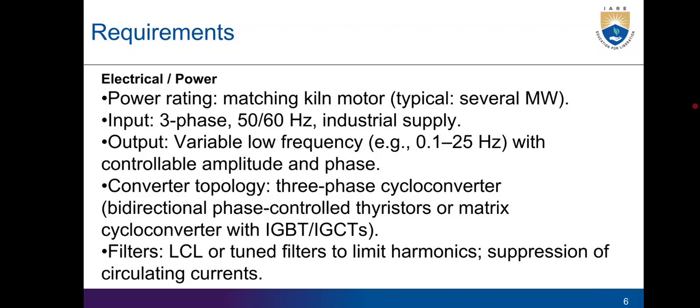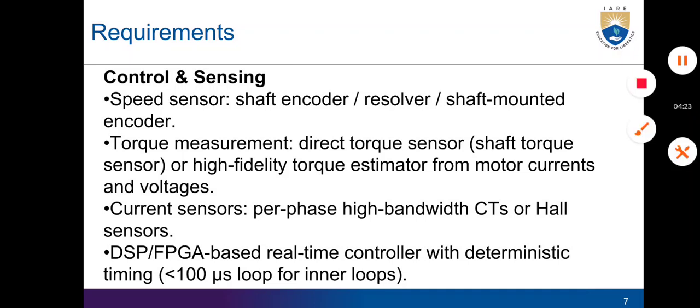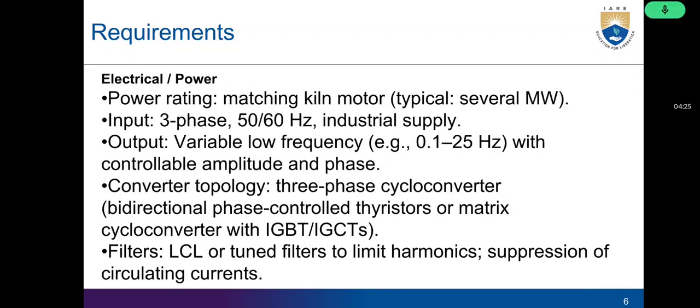Converter topology: 3-phase cycloconverter, bidirectional phase controlled thyristors or matrix cycloconverter with IGBTs and IGCTs. Filters: LCL or tuned filters to limit harmonics and suppress circulating current.